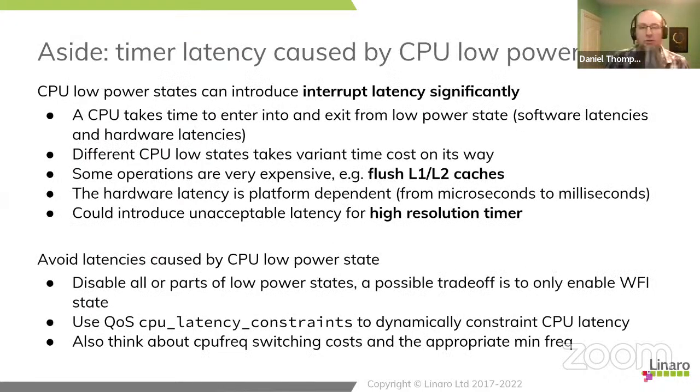So this is mostly just kind of warnings, and there are multiple mechanisms you can use to avoid it. I mean, the simplest thing is you can avoid some of the low power machinery and not use it. So if you have a system where you've looked at your real-time specification, you've recognized that going into a very deep sleep state means that it's possible to meet the specification, then you can disable that sleep state.